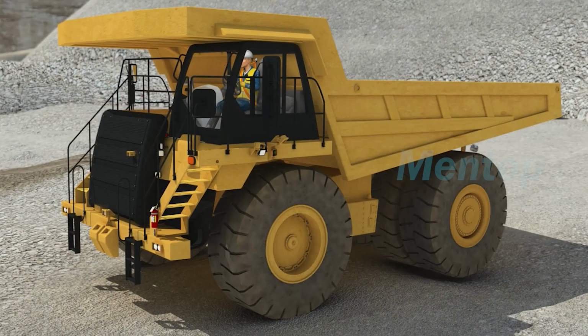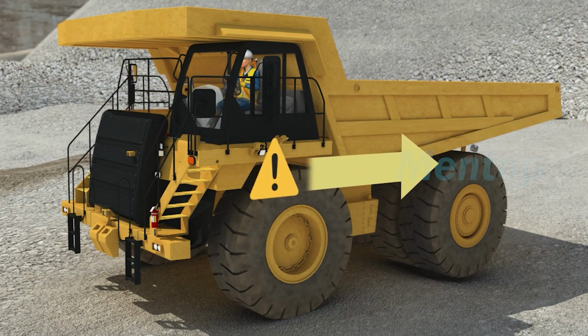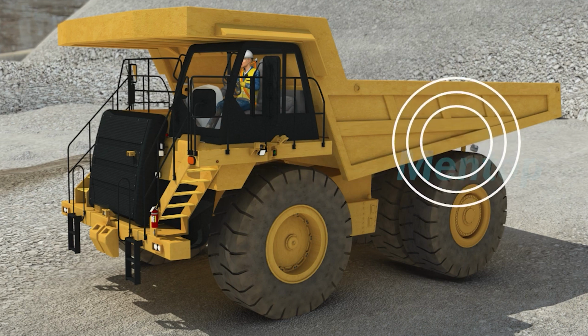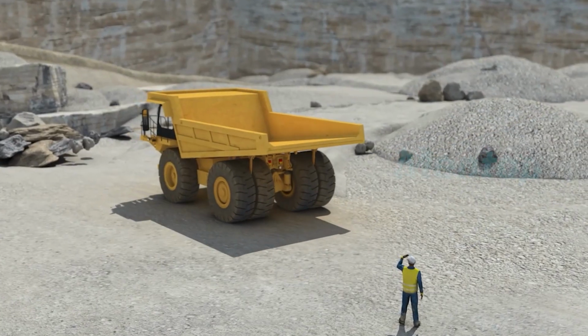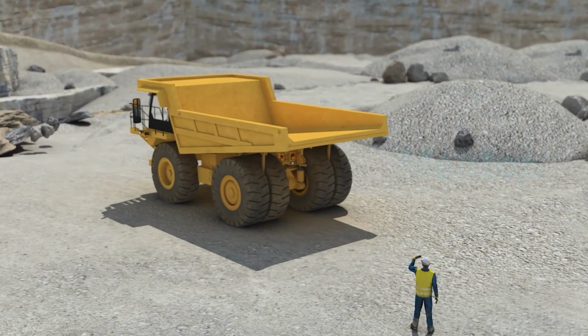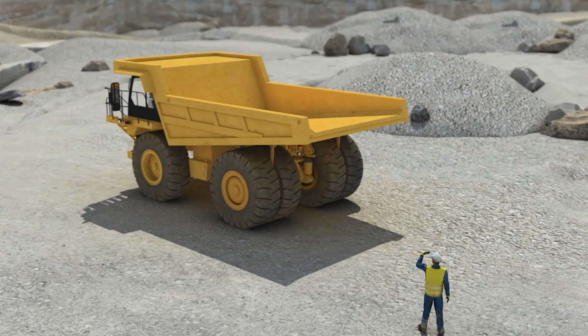Your employer should ensure all earth-moving or compacting equipment with obstructed views do not operate in reverse gear unless the equipment has a reverse signal alarm or a safety monitor on the ground. If the equipment doesn't have a reverse signal alarm loud enough to be heard against the surrounding noise level, the employer will designate a worker to signal when it's safe to back up when the operator has an obstructed view to the rear.